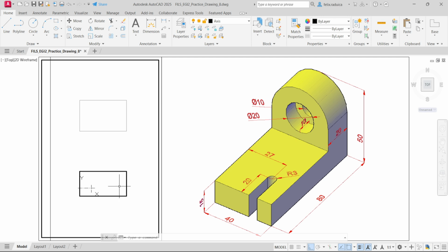So let me give the line command and snap to the middle here and give it like that, 23, and tap enter again, and then click on it, grab onto this grip and give it another 3 from the keyboard and escape. And these are the axes for my top view.